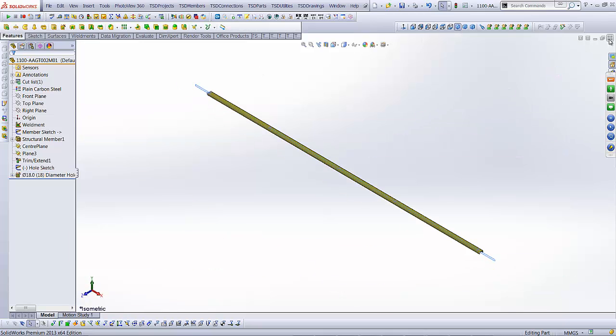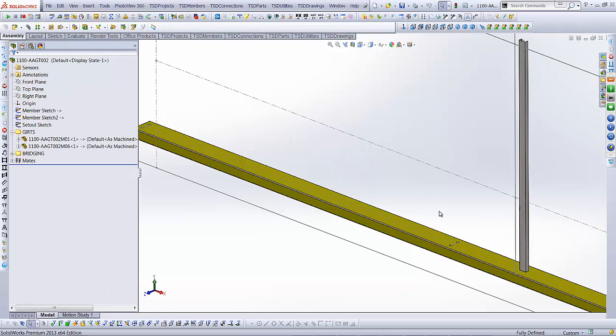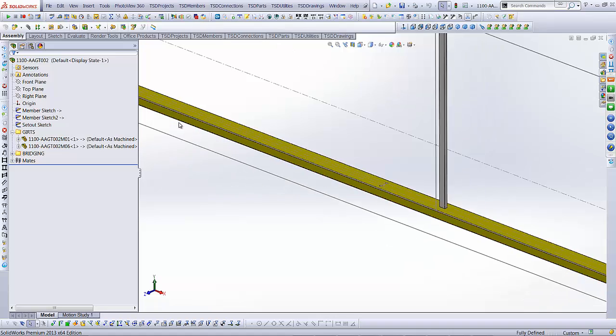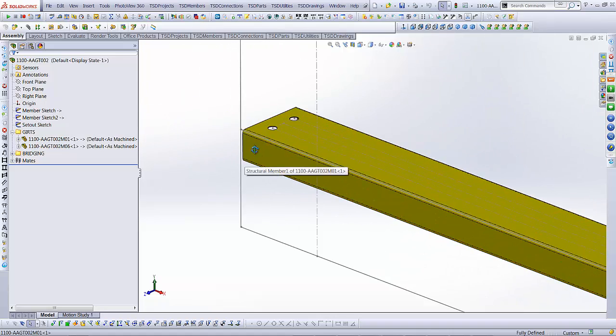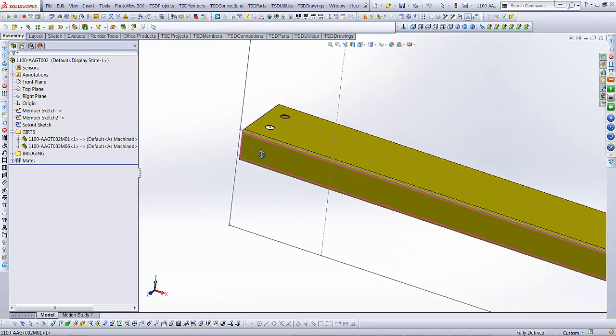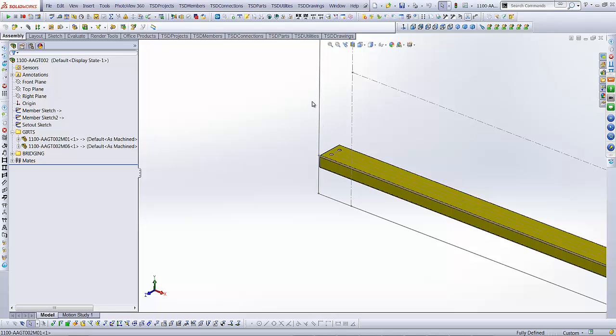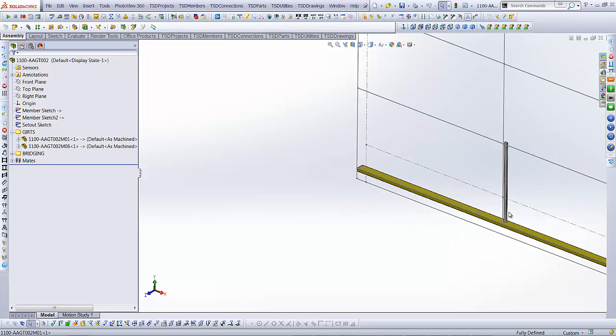We can go back to the girt and we can lock it onto our driving sketch. Okay, now the girt itself, if we go in, you'll notice that this end has got a stock standard 5mm cut, 35mm in. We're not actually going to attach that to anything at this stage. We're just going to leave it as it is. You'll probably find that the column sketch here will go outside anyway, because the column's going to be out here in the center, 5mm off.